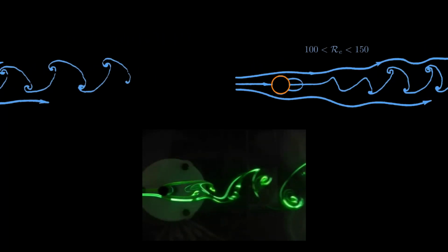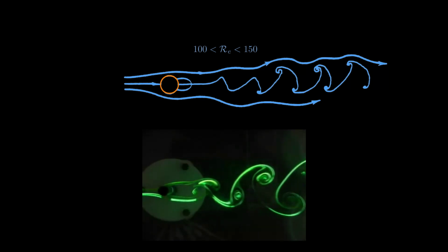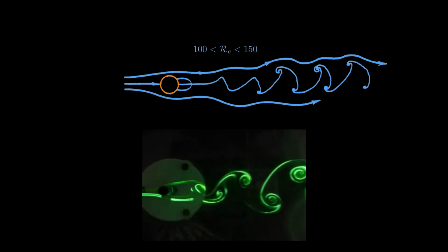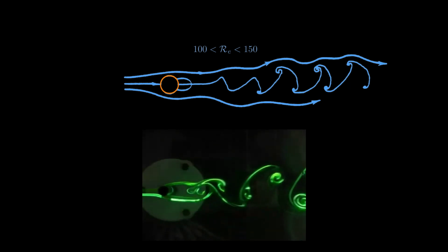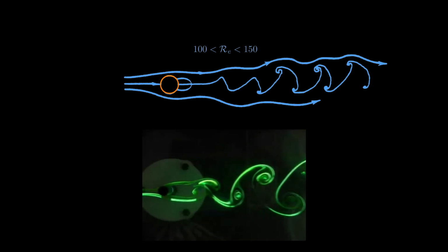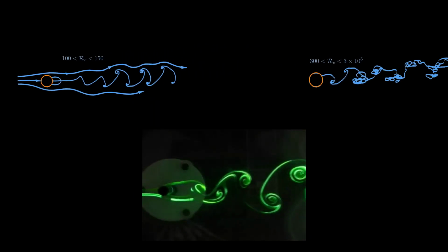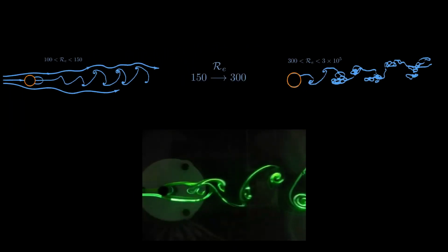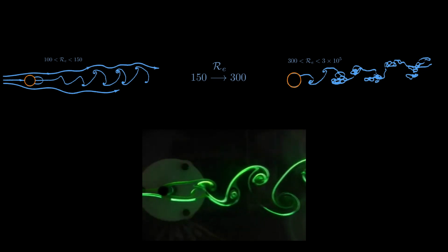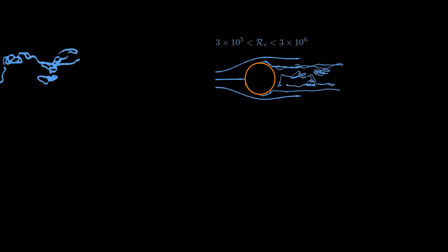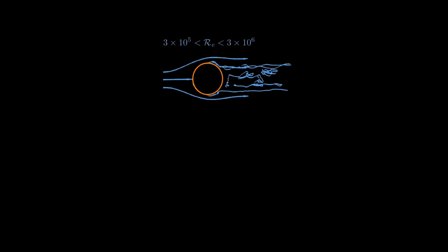At higher values of the Reynolds number, the vortex detachment continues to be observed with an additional recirculation zone behind the cylinder. Then, the vortex wake becomes progressively turbulent. This progressive transition takes place up to a Reynolds number of about 400. From this value, the von Karman wake is fully turbulent and this regime persists until a Reynolds number equal about 30,000.